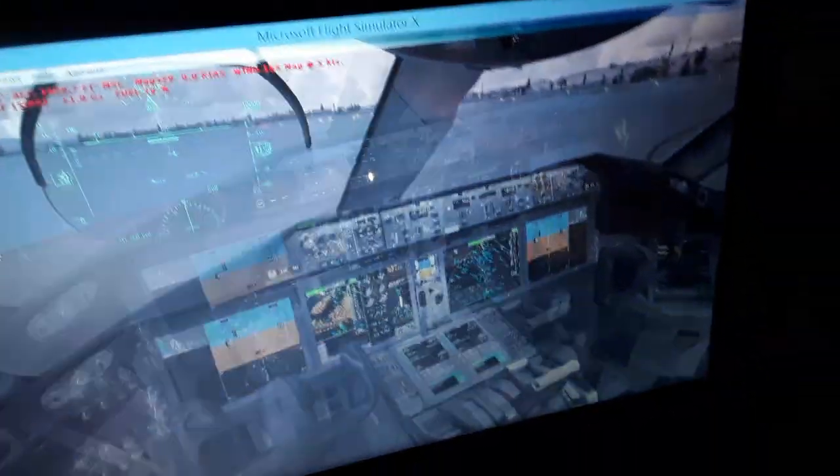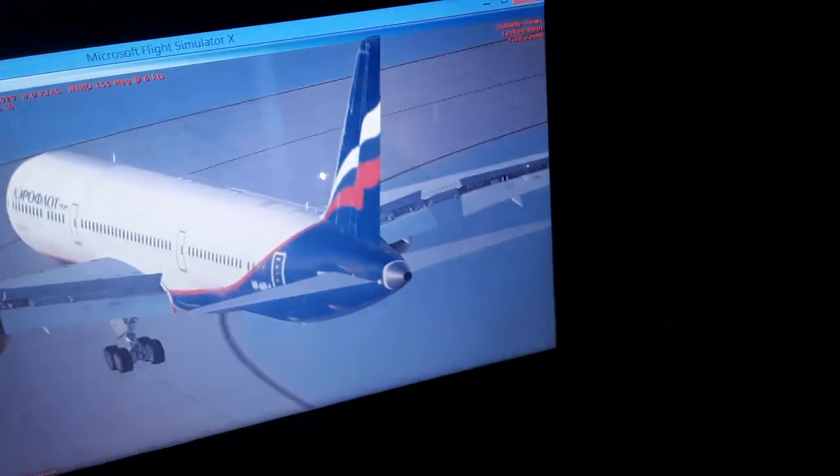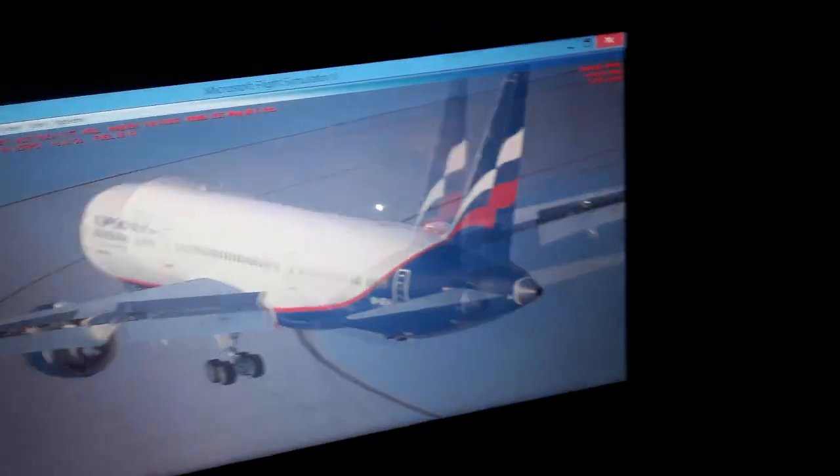Some aircraft like the Boeing 737, it has the trim wheel. Also all the Airbus aircraft have trim wheels. The newer Boeing aircraft that have only trim tabs or trim switches, like the Boeing 787 or the Boeing 777 or 767, 757, 747. So the trim switches are used for the horizontal stabilizer over here to trim the elevator, as you can see. So we trim like this, pitch up and pitch down. It balances the aircraft in flight very easy.